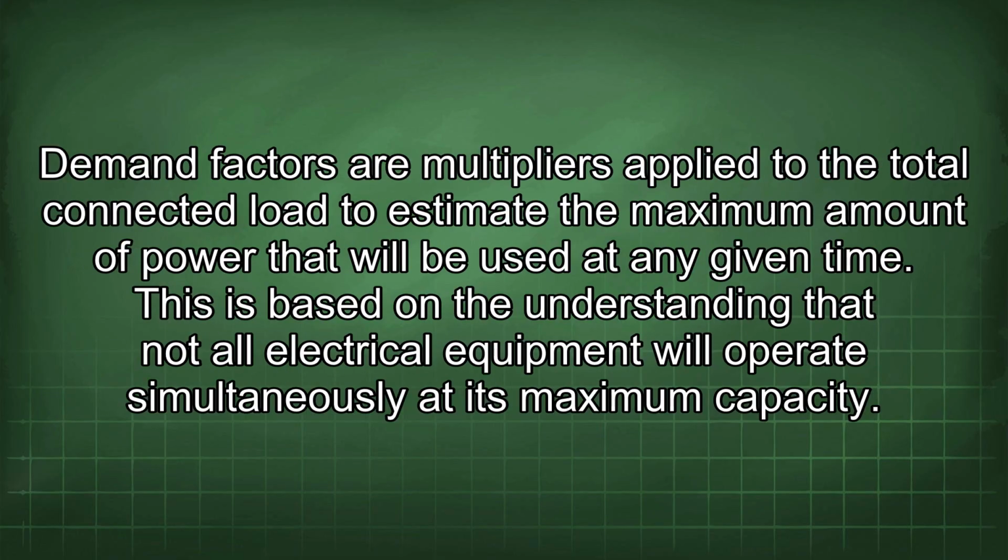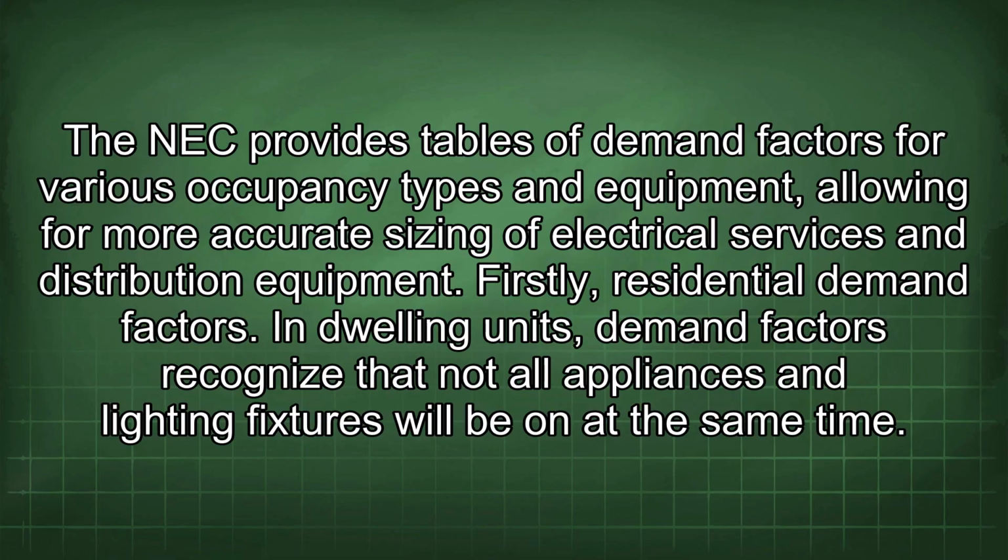Demand factors are multipliers applied to the total connected load to estimate the maximum amount of power that will be used at any given time. This is based on the understanding that not all electrical equipment will operate simultaneously at its maximum capacity. The NEC provides tables of demand factors for various occupancy types and equipment, allowing for more accurate sizing of electrical services and distribution equipment. Firstly, residential demand factors.